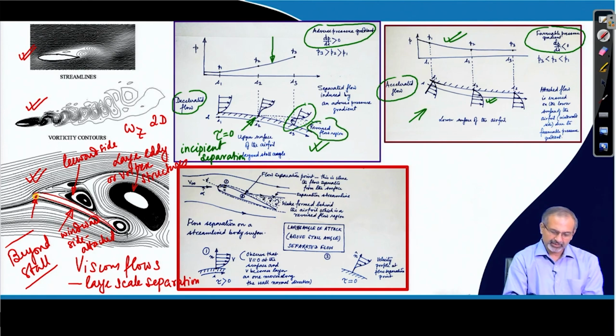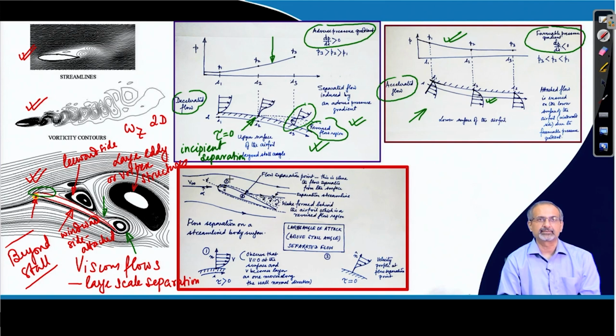So, all that once again comes back to you when you look at the numerical results. So, here you can see large pockets of separated flow where it has even gone beyond an ordered structure like this, because very close to the leading edge itself the flow seems to have separated. So, it is like a leading edge separation which is in action currently.